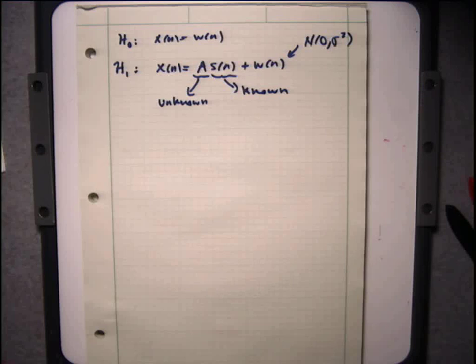And so one of the questions one would like to ask is, as I said before, the generalized likelihood ratio test generally doesn't have any optimality properties. So if you do what I suggested in the last couple of pages, you don't necessarily end up with a detector that, for a fixed false alarm, has the highest probability of detection.